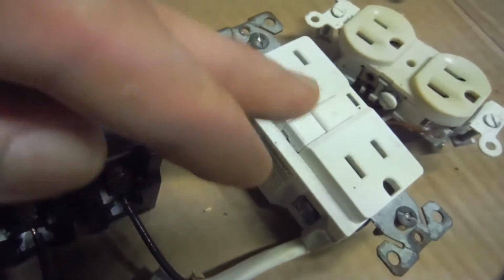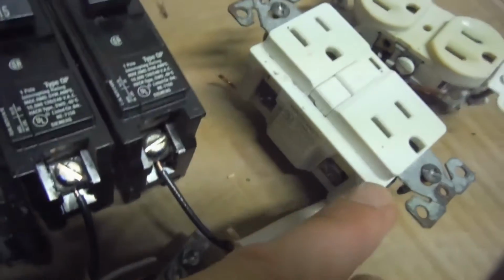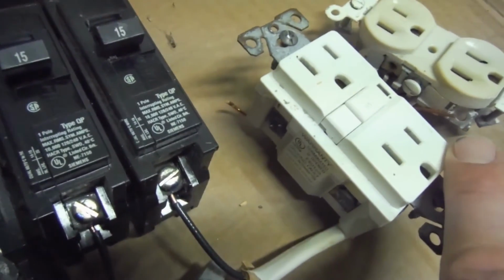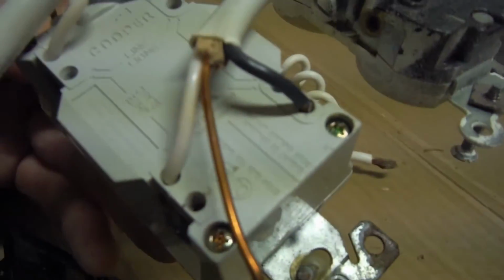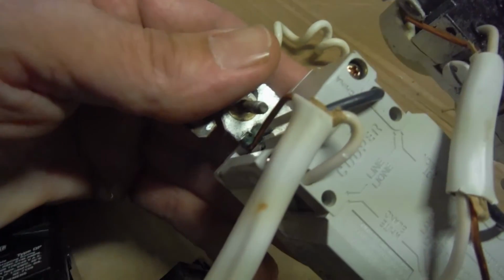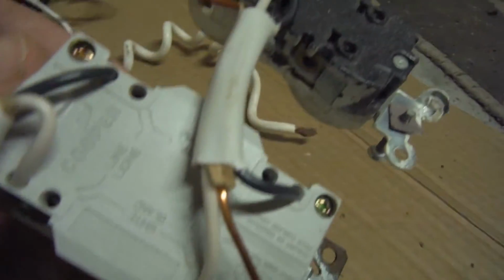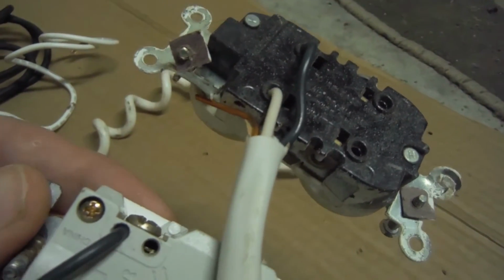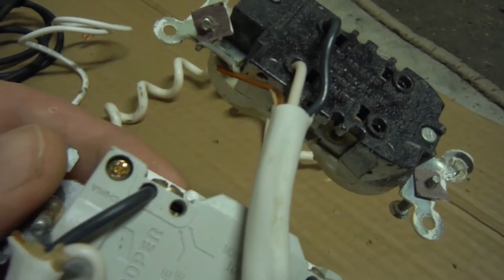But pretty much what it does is the same thing. Comes in, hot side hot, neutral side neutral. And this one actually, if you look, you've got two different sides. Line right here where it's plugged in, and the other side is called load. Oh, it's hidden right behind there. Kind of can see it. But anyway, line would be your line coming in from the breaker. Your load would be your load going out to anything else beyond the GFCI that you want GFCI protected.